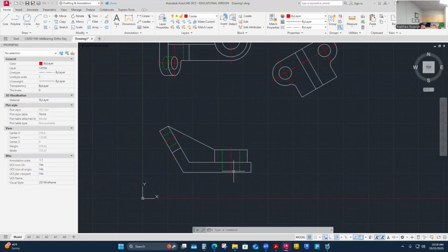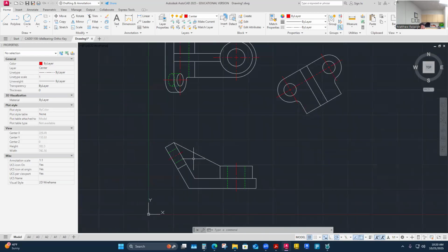So those are strong controls. Nice flat surfaces and nice true axes and centerline planes are better controls than some weird outside surface that's slightly contoured or an edge. Not that it can't be. It's just that if I have a better selection, I would choose it until I absolutely can't. And then I establish an edge maybe, or a real radius tangent point, as one. It's not that I can't, but anyway, good call.